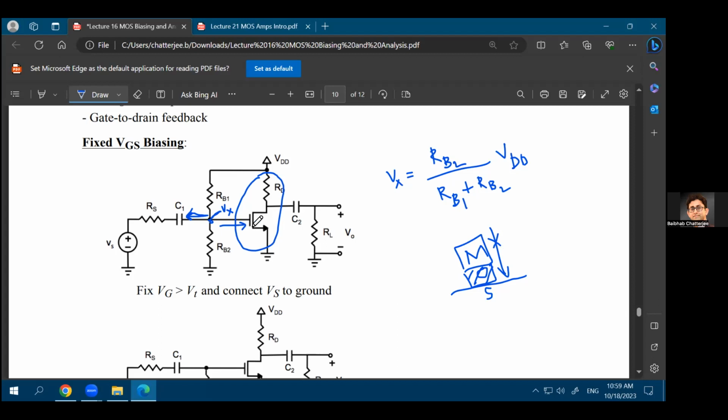Now you can sort of guess why. If you create an op-amp for which the input stages go to the gate of a MOSFET, there cannot be any current flow into that gate, because at the gate of the MOSFET you have silicon dioxide, which is an insulator. There cannot be any current flow through an insulator. There could be a very small amount of leakage, but let's ignore leakage at this point.